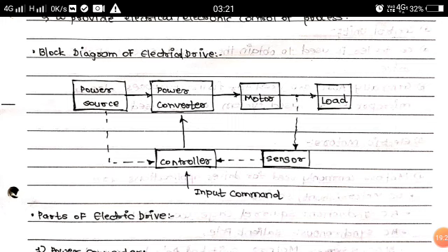Otherwise, it is a good amount of electrical signal, meaning some standard voltage, 5 volts or less than 5 volts or like that. So the sensor is giving the controller some electrical signal which is proportional to the quantity to be controlled. Then there is the input command to the controller. What is that input command? The input command is the required quantity which we are controlling. So in our previous example, the human being's comfort level was set in his mind. It was the input command. I want this much comfort.